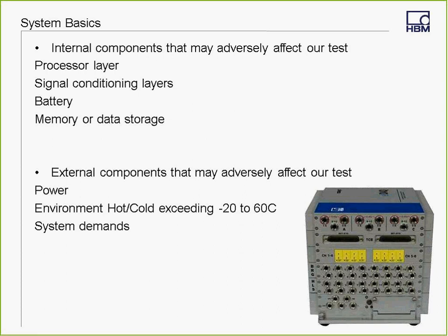Internal components that may adversely affect our test would be the processor layer, signal conditioning layers, the battery as we've seen, and then memory or data storage. External components that may adversely affect our test would be power, as the eDAQ must be powered by an external source, and inadequate power is a common problem.